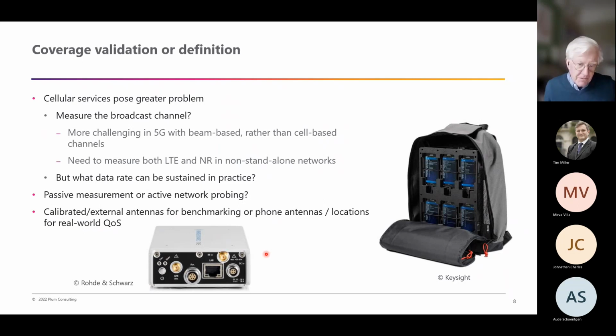So you have beams that can sweep across the coverage area of a particular base station, and you no longer have a fixed signal power emanating from the base station. So with 5G systems, you need to do a much more complicated search for the beams of the base stations as they scan, looking for new users, and to process that very rapidly time-changing behavior.